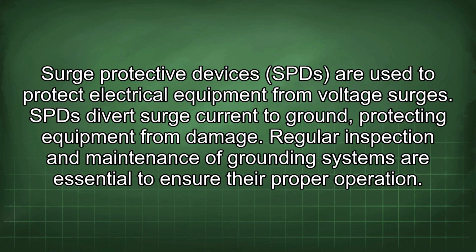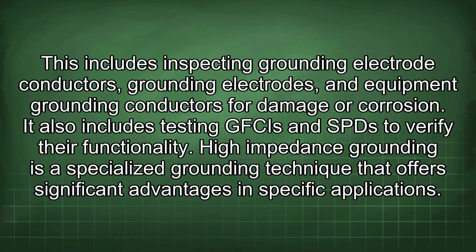Regular inspection and maintenance of grounding systems are essential to ensure their proper operation. This includes inspecting grounding electrode conductors, grounding electrodes, and equipment grounding conductors for damage or corrosion. It also includes testing GFCIs and SPD to verify their functionality.